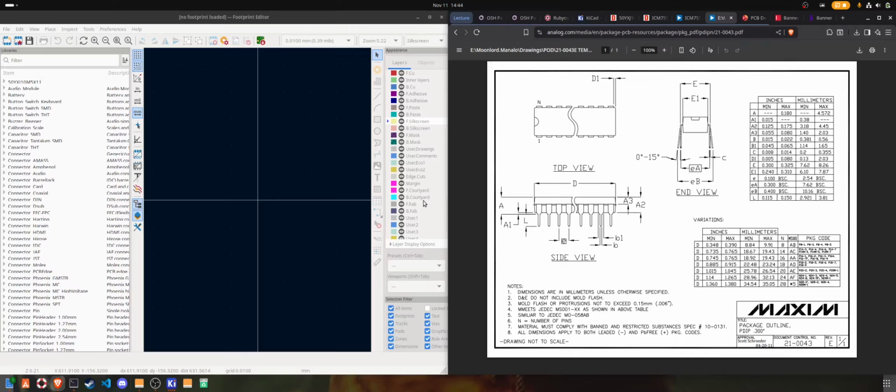I already figured out all the coordinates and where you need to place everything, so I'm just going to walk through it. But just a basic gist of what's happening is, in our footprint editor, we have our coordinate system for KiCad, and each pin is going to be placed on this coordinate system. This is the positive X direction, and this is the positive Y direction, and positive Y goes down because the coordinate system for KiCad is just inverted.